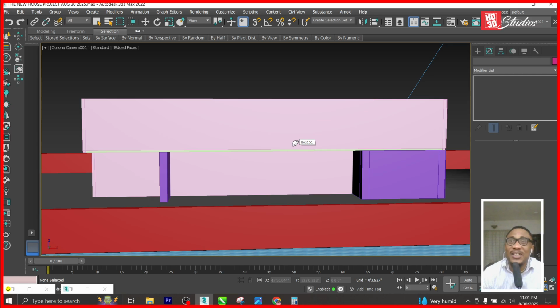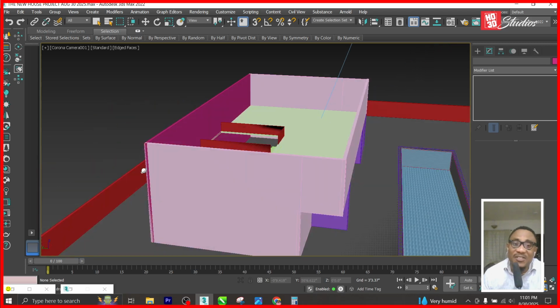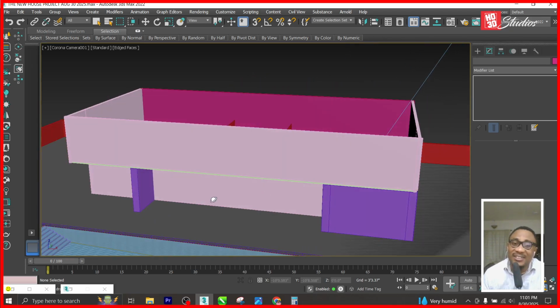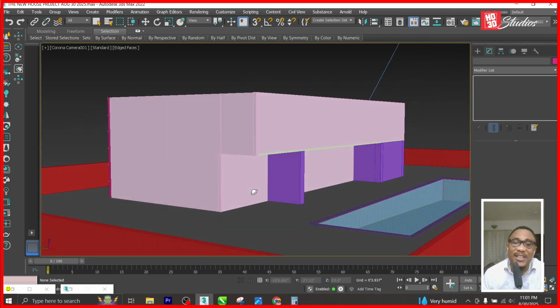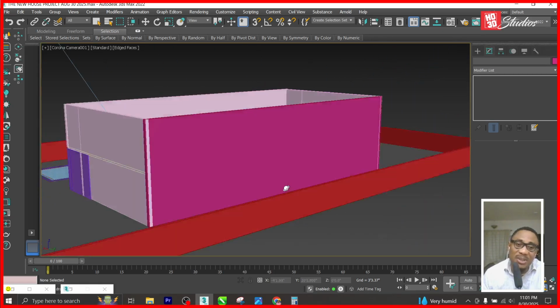The structural engineer will also check the soil integrity to be sure that the soil has the bearing capacity. The soil can carry the weight of the building you're putting on it. This is a 28.5-foot tall house, 100-foot wide, 50-foot deep, and the soil cannot be loose. All these things come into play. So it's not just about designing a building.